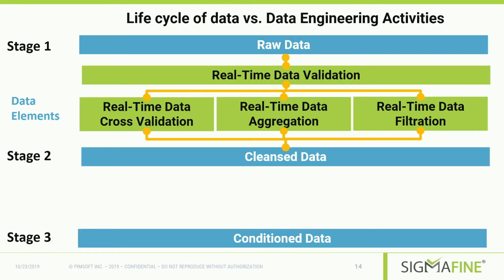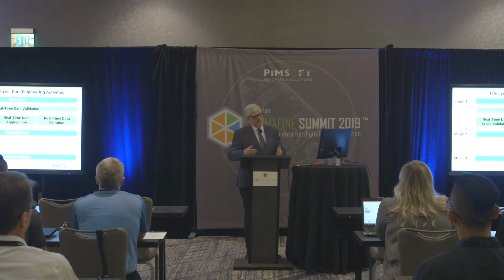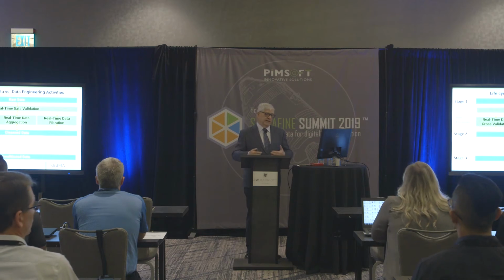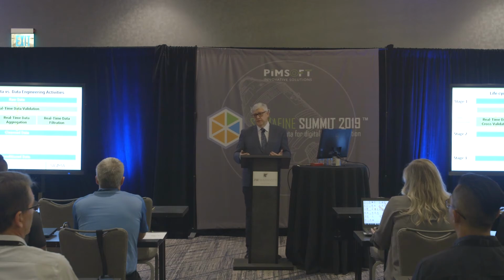Then we have other more advanced capabilities, which would be real-time cross-validation. So if you want to do some pressure, temperature compensation on the run, you can do that because it's easy, because you have an equation, you run it, and it's not going to consume a lot of resources. You can do a bunch of aggregations on the run as well, just to transform the data into a way that's going to be more usable. You can do some filtration. There's a lot that has been written about all these things, but to me, that's our toolbox. That's our toolbox to actually work on the data and continuously find ways to improve it and get to a point where we've done the best job we can to clean up the data.